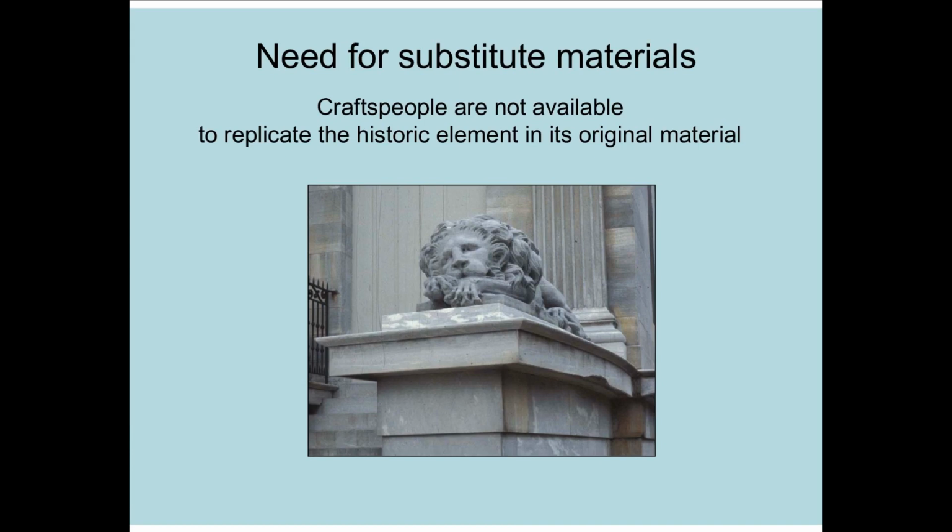The unavailability of historic craft techniques and lack of skilled artisans complicate any rehabilitation project. This is particularly true for intricate ornamental work such as carved wood, wrought iron, or carved stone, such as seen in the intricate carving of the lion in this example. Efforts should always be made, prior to replacement, to seek out artisans who may be able to repair ornamental elements and thereby save the historic features in place.